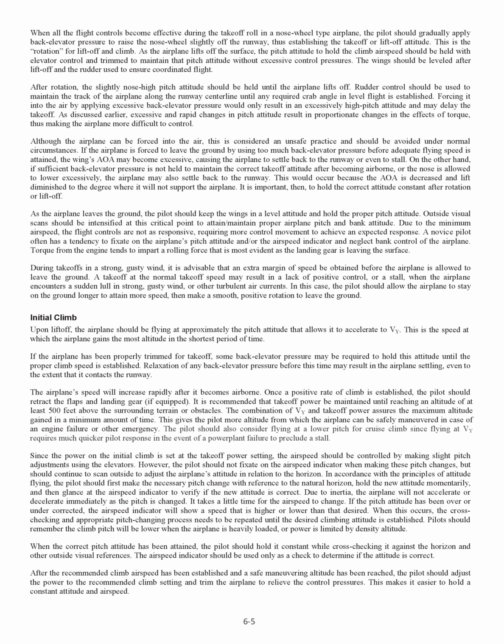This gives the pilot more altitude from which the airplane can be safely maneuvered in case of an engine failure or other emergency. The pilot should also consider flying at a lower pitch for cruise climb, since flying at Vy requires much quicker pilot response in the event of a power plant failure to preclude a stall.